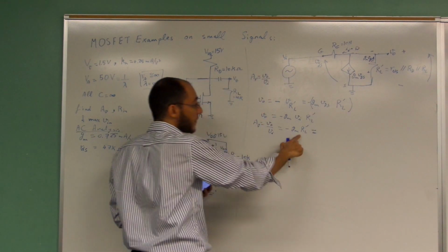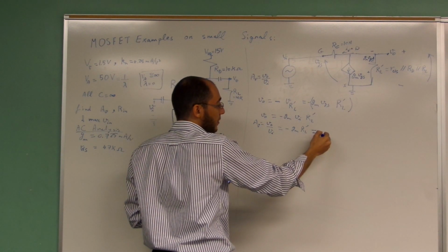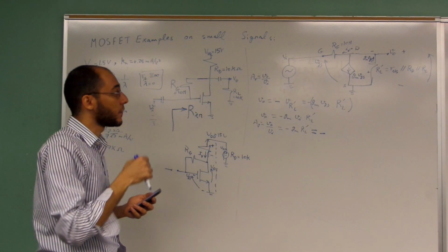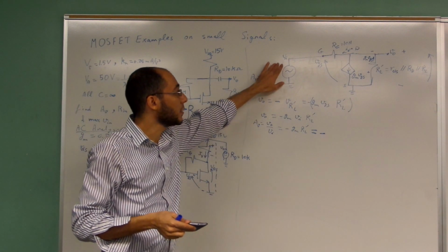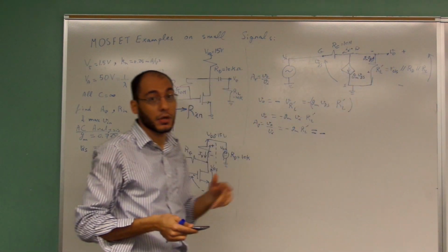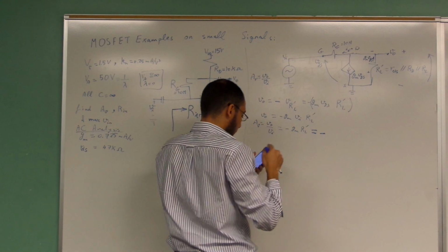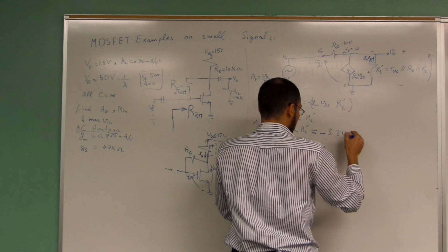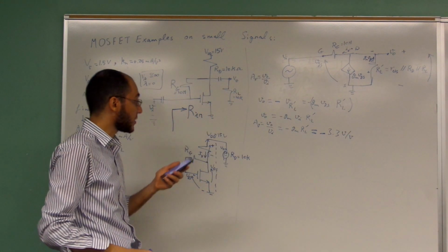So you recall that this value is not a positive value, it's a negative value. And this is valid. Why? Because you expect that the transistor usually has a negative sign. When you input here a sine or a cosine, you get here the inverted version of this value. The value is AV equals negative 3.3 volts per volt. Whether you put volts per volt or you do not put it, it doesn't really matter.